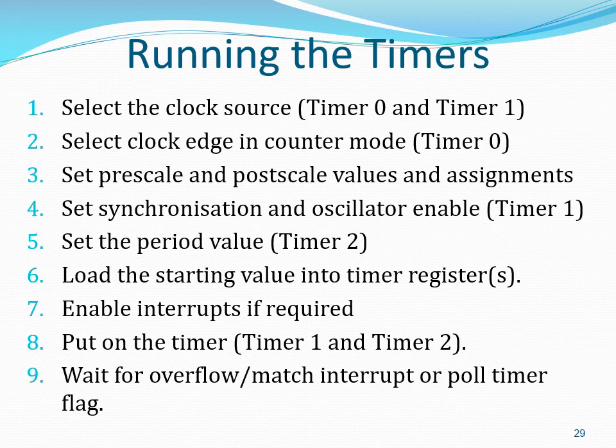Number 3, set the prescale and postscale values and assignments as relevant. Number 4, set synchronization and oscillator enable states. This only applies to timer 1. Number 5, set the period value by writing into the period register. This only applies to timer 2.